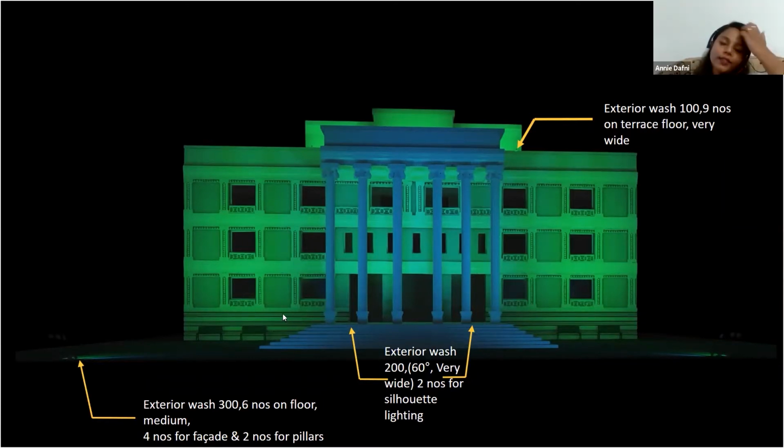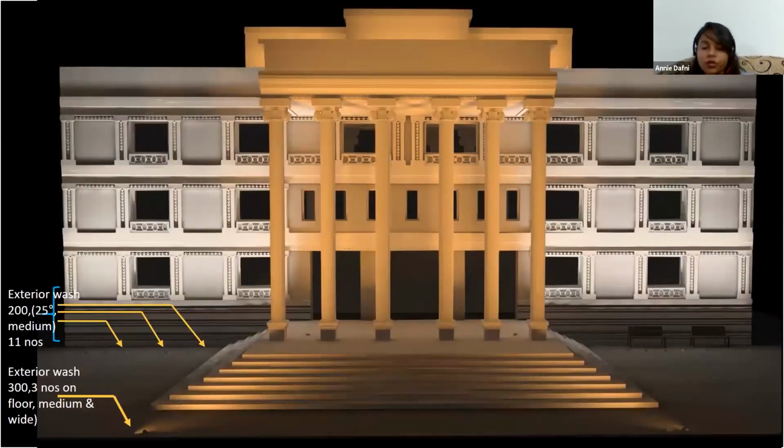So again, in all of these examples, the floodlighting technique, firstly, the problem of glare still persists at very minimal angles, like when you're looking at them perpendicularly, maybe out of the window. And secondly, for people walking by in between the fixture and the wall, these people might cast a shadow on the facade. And thirdly, maybe there is not enough provision to place the fixtures at such a far distance from the building. So in order to overcome these 3 cases, the only way is to move the fixture very close to the building and still get a uniform distribution or lighting level on the facade.